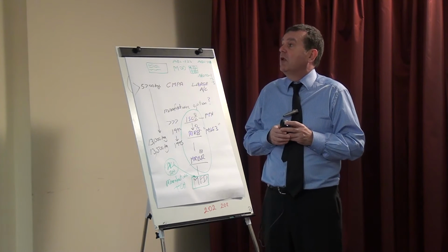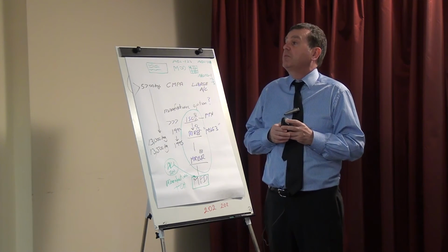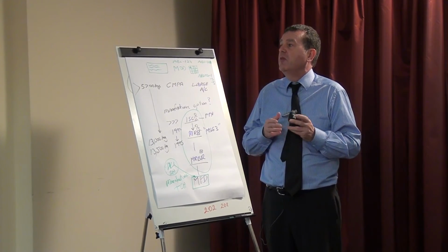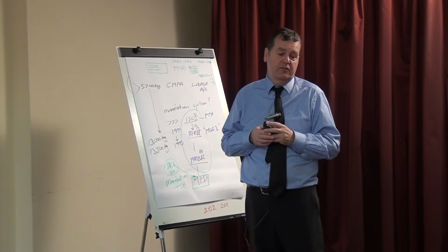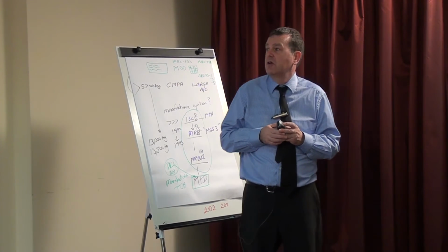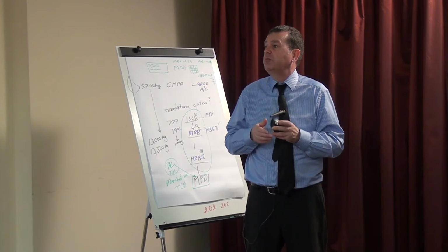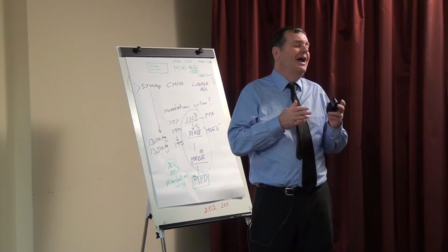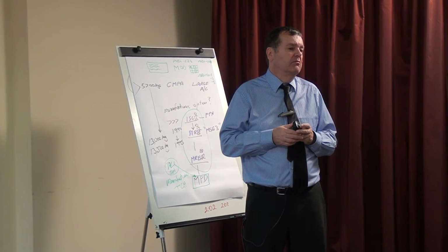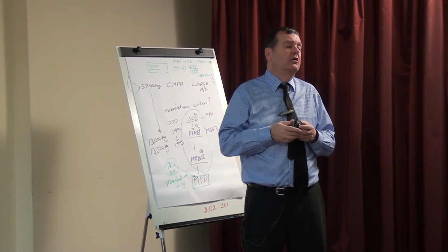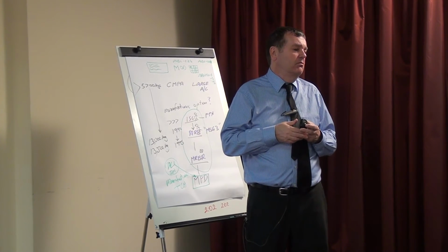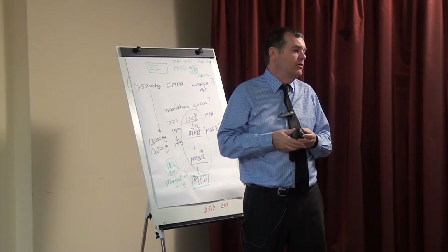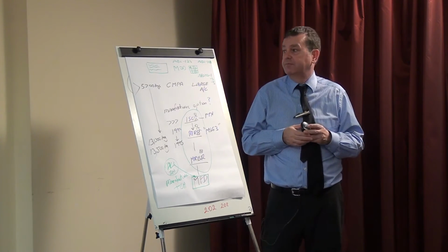The component level used a logic process which considered failures starting at the component level and moving up, with a focus on understanding that all aircraft, engines and components reach a period when they should be discarded or overhauled and returned to a as new condition. And when we do an overhaul, it's a restoration. It may not, in actual fact, return it completely to the original, but it's as close as we can get.